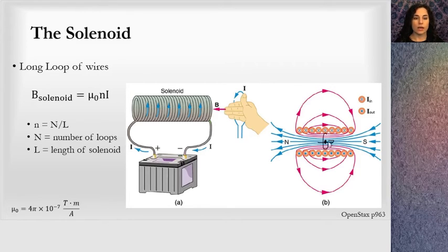And so that's why we like solenoids. At the ends, it's not so reliable. You have not a constant magnetic field at the ends. But right in the center, all the way across the center, you have a constant magnetic field. In a lab, I would have people connect a slinky up to a voltage supply. And then you can use a Hall probe in order to measure the magnetic field in the center. It's a really cool experiment.